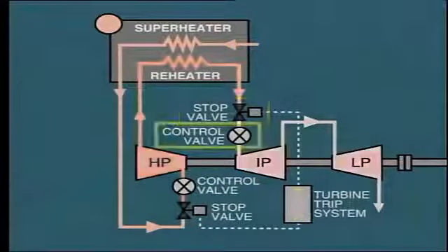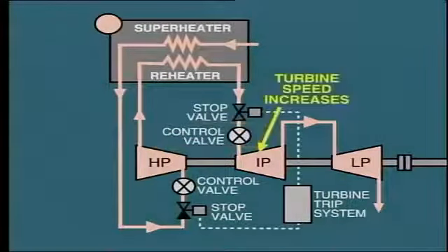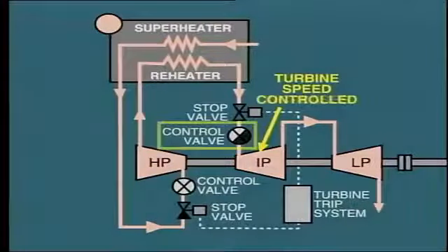Similarly, the reheat intercept valve is fitted to assist in precise control of the turbine. The intercept valve is in fact a control valve that normally remains wide open, allowing all of the turbine control to be carried out by the main steam control valves. However, in the case of a partial load rejection, perhaps due to a transmission line trip, operation of the main steam control valves by governor action may not be sufficient to hold the turbine speed down. Again, this is because of the entrained reheat steam continuing to pass for a few minutes through the intermediate and low pressure turbines. The intercept valve prevents this.